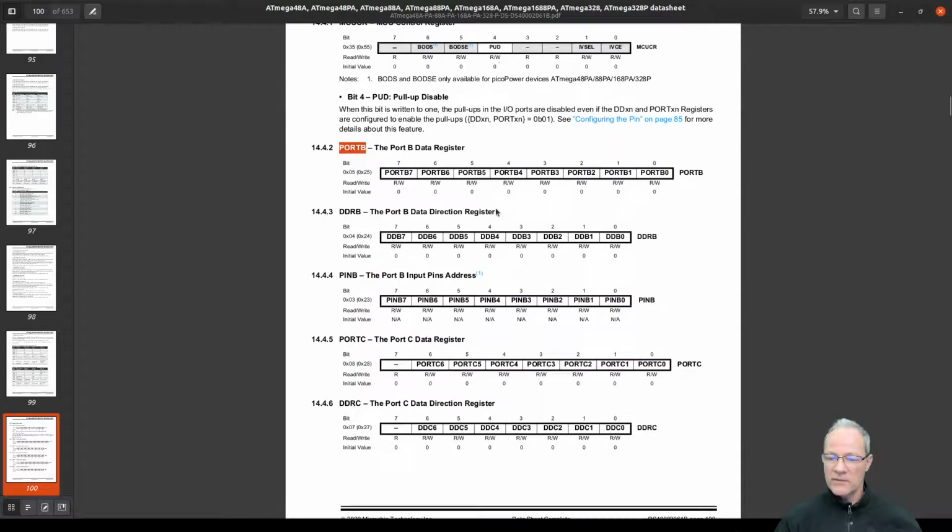And here's the port B register, for example, right? So every register has a certain number of bits. In this case, we are using all 8 bits. And these bits have certain values, so port B7, port B6, port B5. So you can sort of access them by this reference. So SBI instruction that I looked earlier, it's not the store byte, but it's rather set bit. And then we can use these values to determine which bit do we want to set or read.